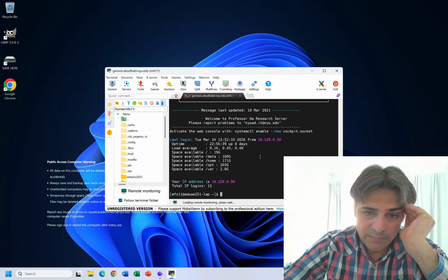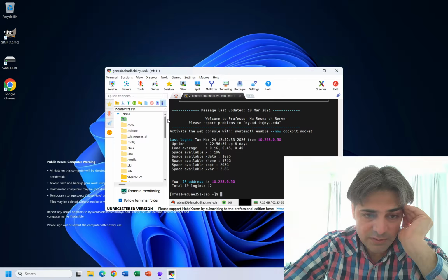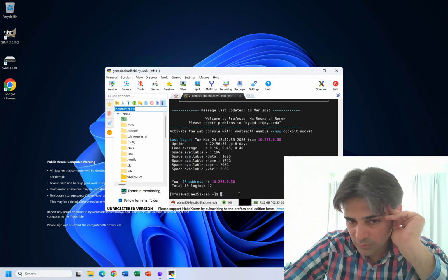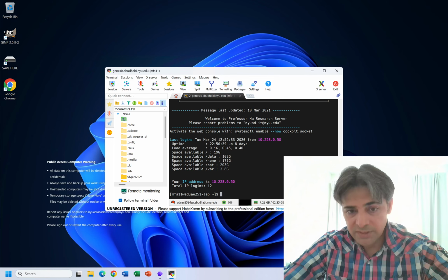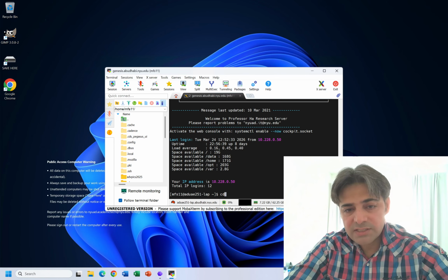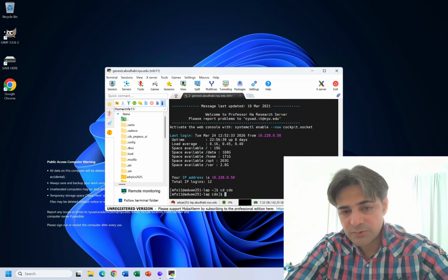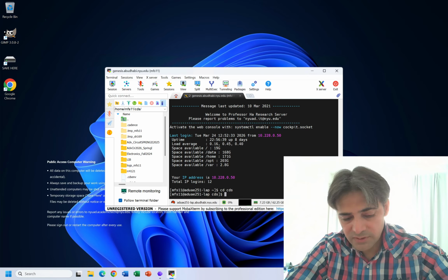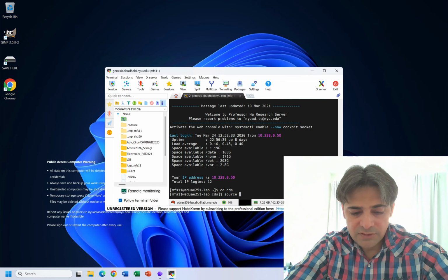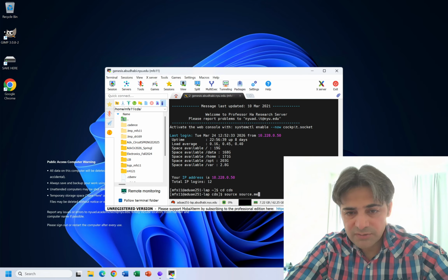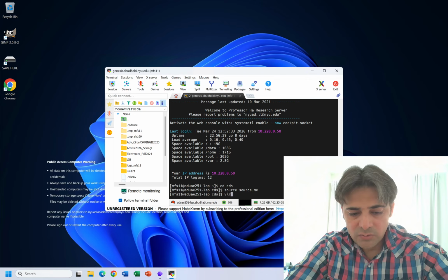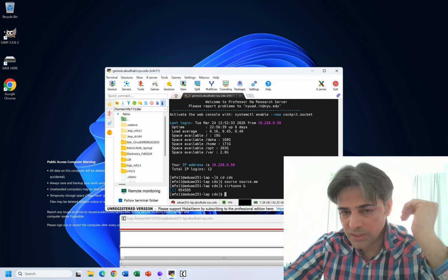Once it logs in, this is what you're going to observe in your system: you will be taken to the home slash your home folder with your net ID. To log into the Cadence, we'll have to change the directory to its main Cadence server, and then this is the command that you will write, the sourcing, and then virtuoso, and this is going to start the Cadence.